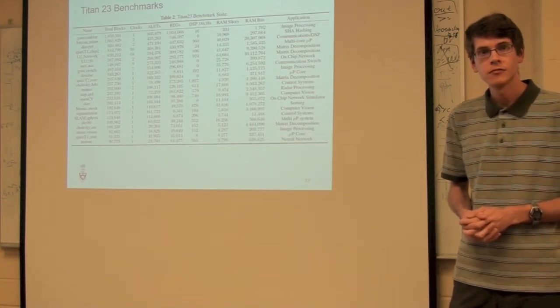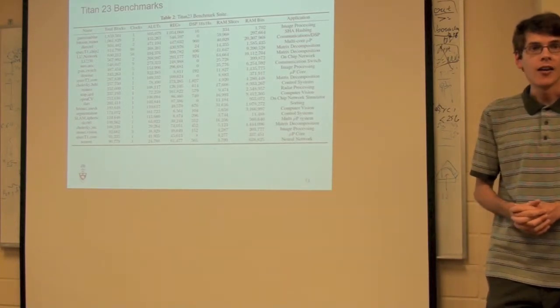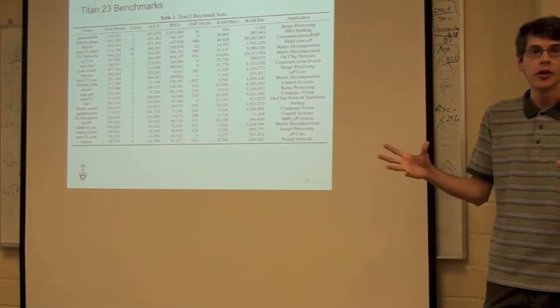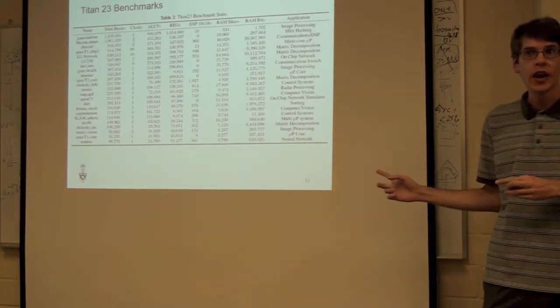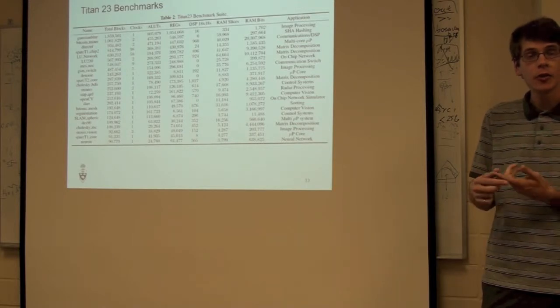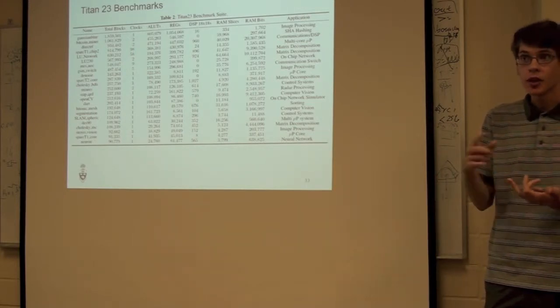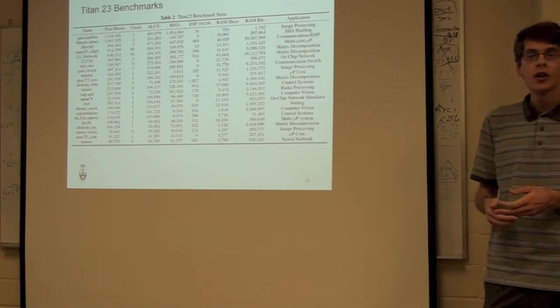One of your future goals is you wanted more flexible routing description inside the block. Well, not inside the block. By that I meant the global routing network. For instance, in Stratix 4 you have 4 types of wires. You have length 4 wires that run horizontal and vertical, and you have length 20 that run horizontal and length 12 that run vertical.